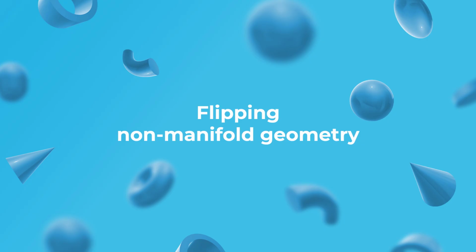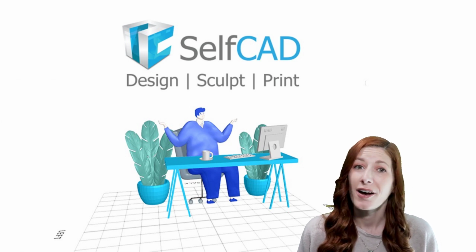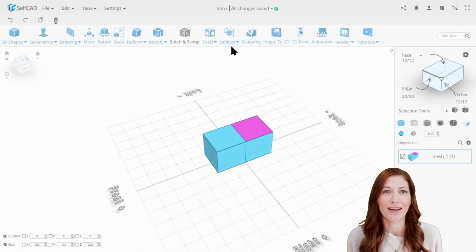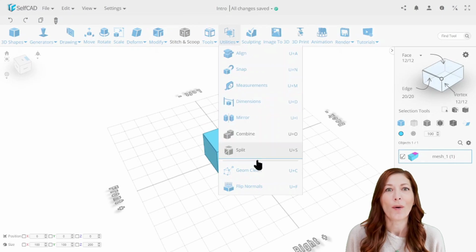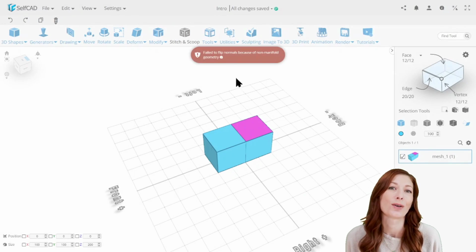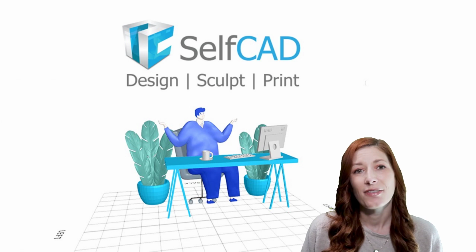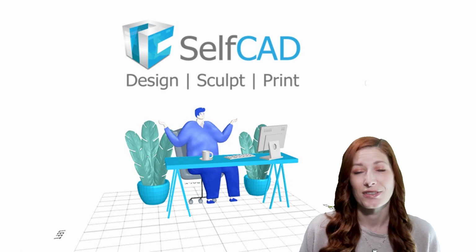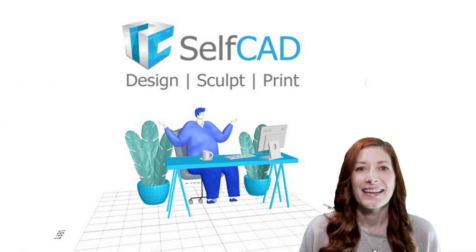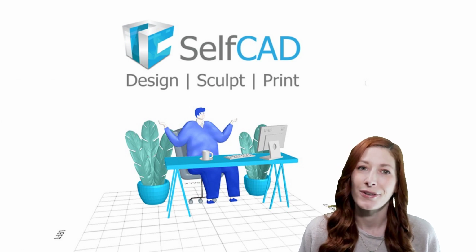Flipping non-manifold geometry. As I said, the most common flipped normals issues result from more complex modeling processes. For example, if you use fill polygons to close a complex shape, or multiple holes at the same time, it can often set some face directions incorrectly, which you can fix with flip normals. However, if the object has other non-manifold issues, they will prevent the tool from restoring the correct orientation. And the attempt to do so will result in the tool showing you a non-manifold alert.